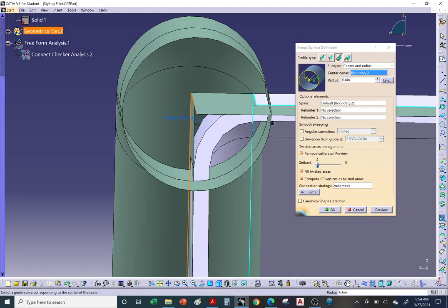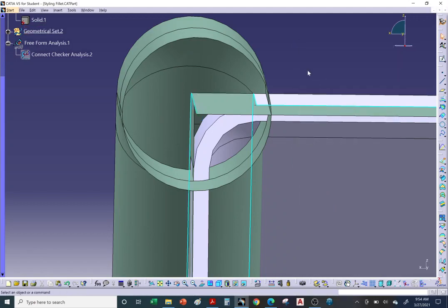And the reason is because we want to start shaping it. Let's take a step back and go with a conic shape, right? Parabolic, hyperbolic in shape. If we start here, it's going to be too sharp. So we want to start a little further back. Okay, so I'm going to hit OK. I'll accept the 0.6. Again, that's about 20% larger than the original 0.5 inch radius fillet.